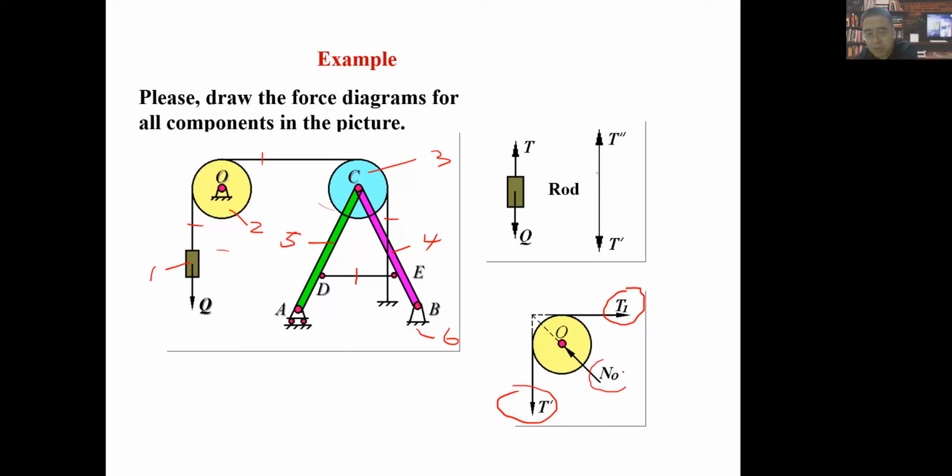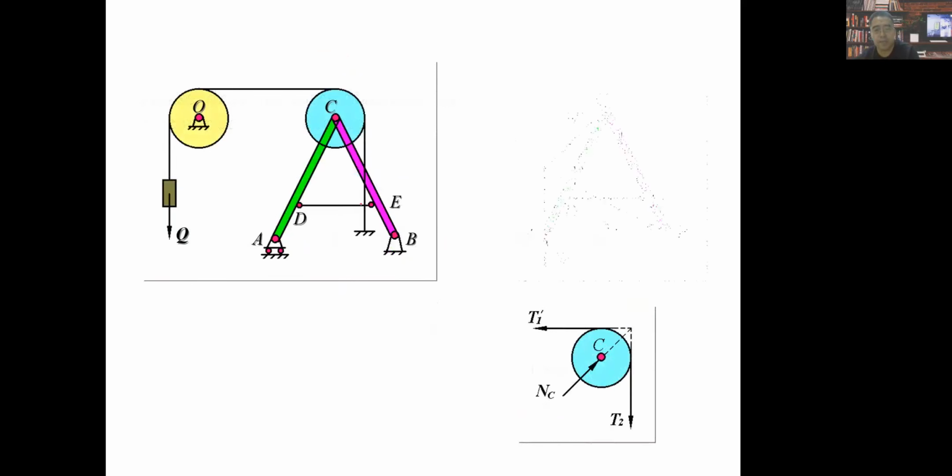If you do not draw like this, you can just figure out it's a fixed hinge. So when we remove this hinge here, we just draw maybe FOX and FOY. Now, if you can only draw like me, you do not use the three-force concurrence theorem. It's okay. It's okay. Because that is also the correct force analysis. So one here, second here. Let's continue and talk about the other object.